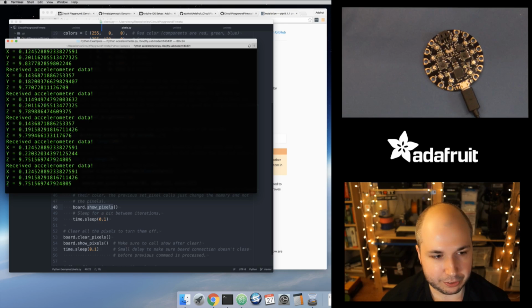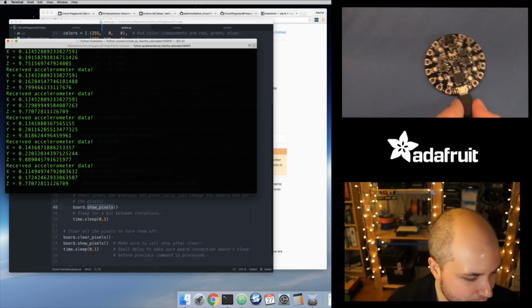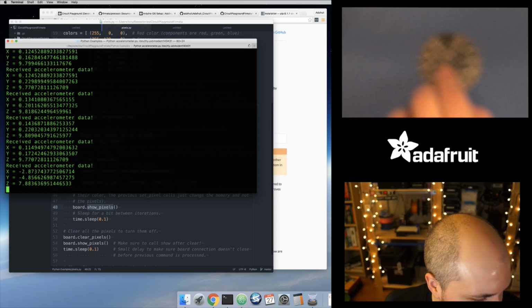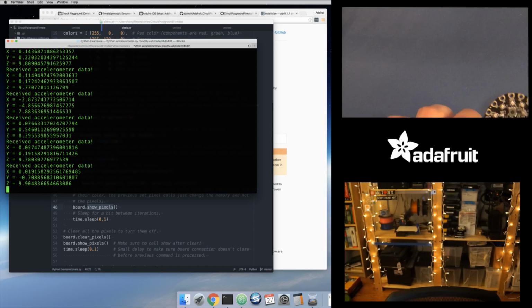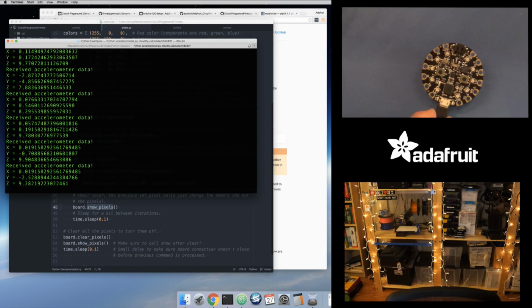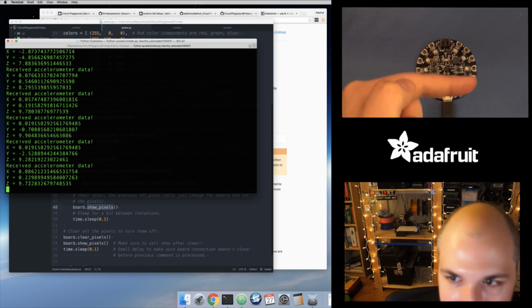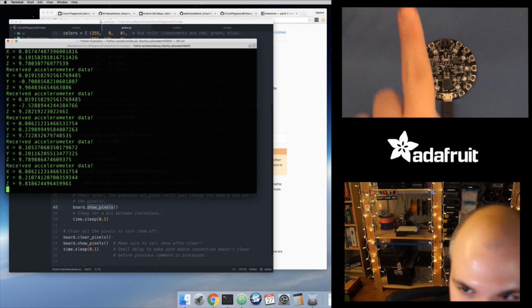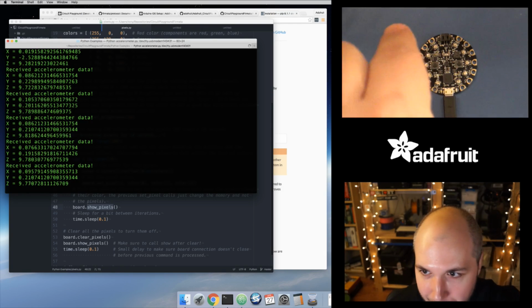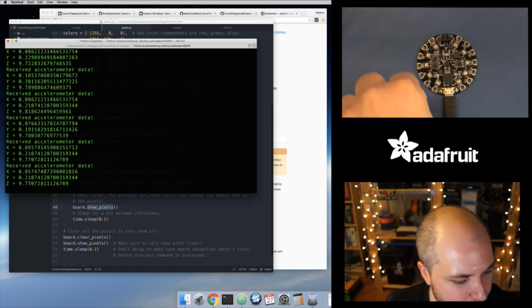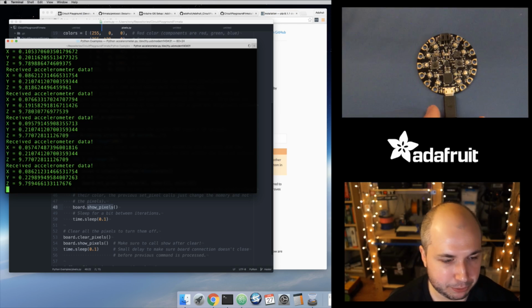And so this is cool. You can actually see my z-axis is reading pretty much bang on 9.8 or 9.7, 9.81 meters per second squared. And the z-axis, like I said, you can see it's printed on the board. There's a tiny little bit of silk screen here that shows z-axis goes up. Let's see, what are the other axes? So it looks like the y-axis goes this way, and then the x-axis goes kind of this way, the way it's oriented right now. And so this makes sense then. Basically gravity is pushing down on this z-axis, and we see that 9.8 meter per second force.